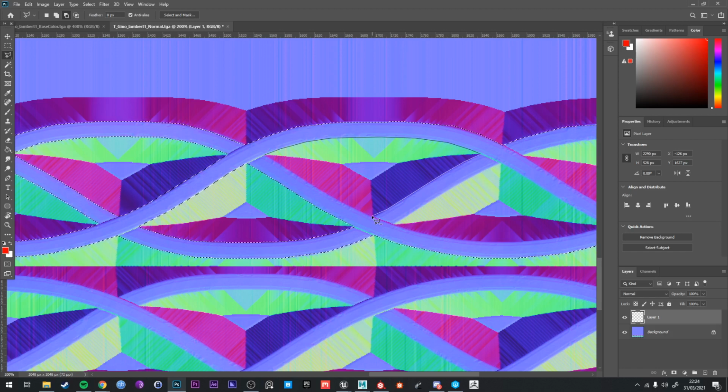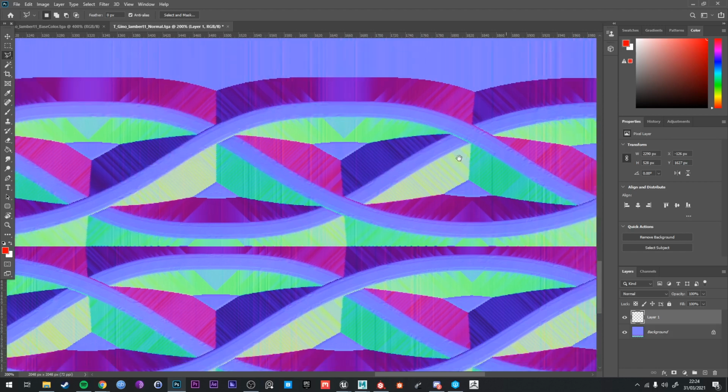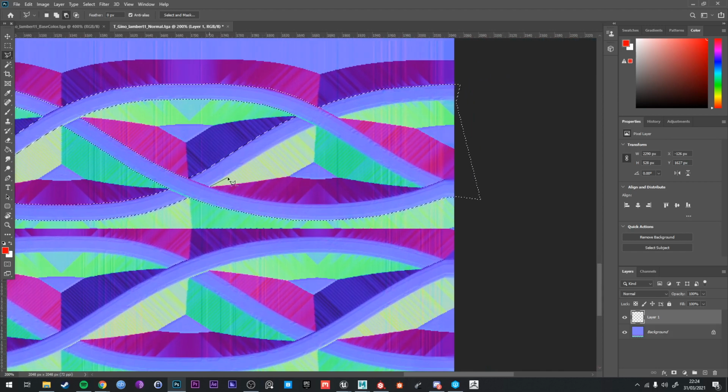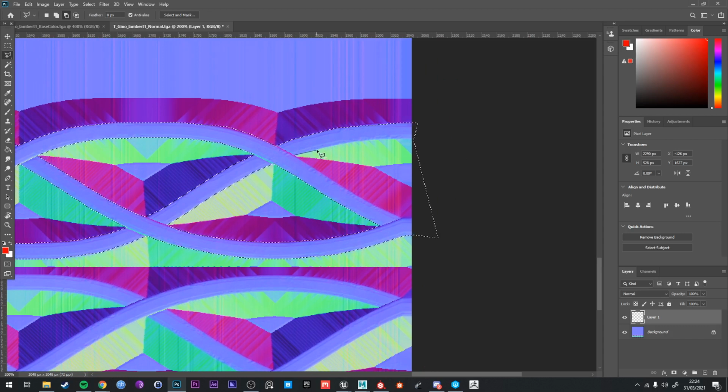There'll be documentation from Adobe on how to do it, but you basically add an opacity channel and you change the shader from PBR Metal Rough to PBR Metal Rough with alpha blending, which basically gives it an alpha channel, aka a mask channel, which can determine the opacity of parts of the material. But in our case, we only need the opacity in Unreal, so there's no point in making the opacity in Painter.